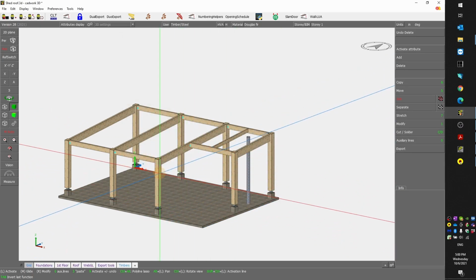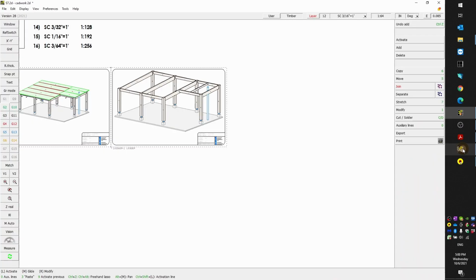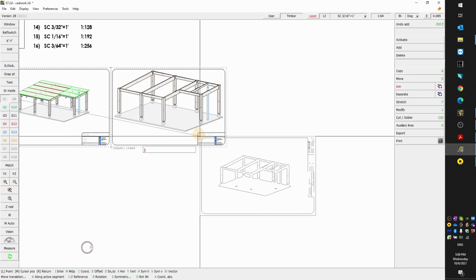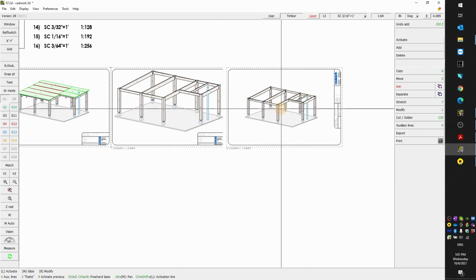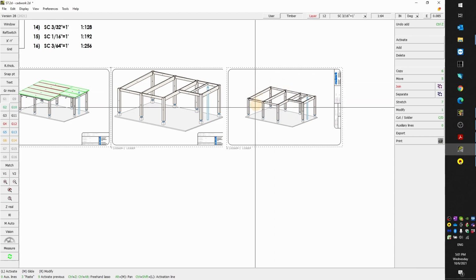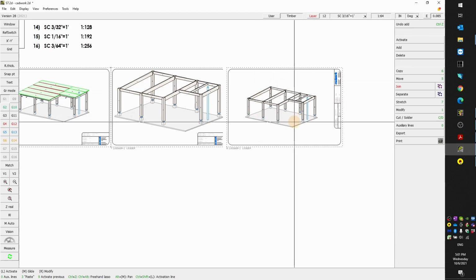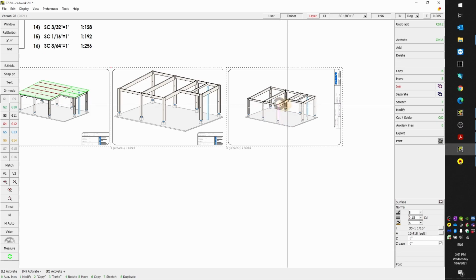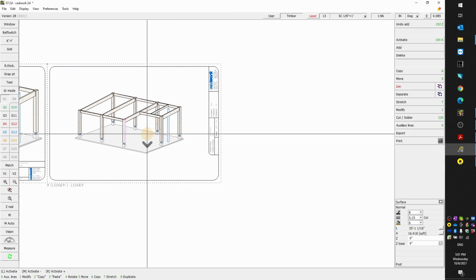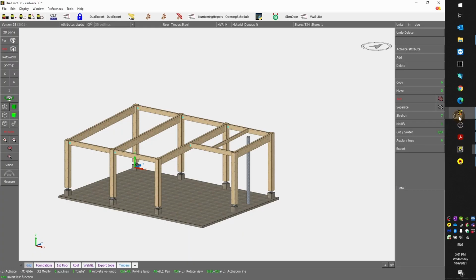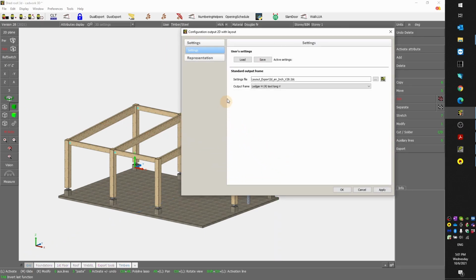The exact same axonometric view, semicolon, and you will see now I have a different title block, and here there is not as much space, so the scale is a little bit different. So here the scale is at an eighth of an inch equals a foot. Great, so let's go back here and again Control F6 to look at the settings.